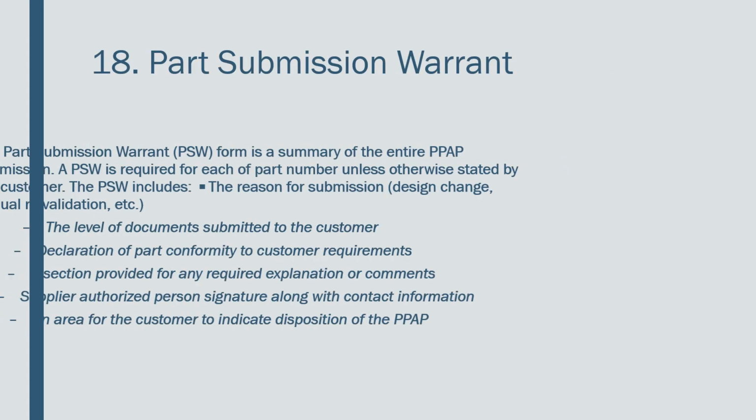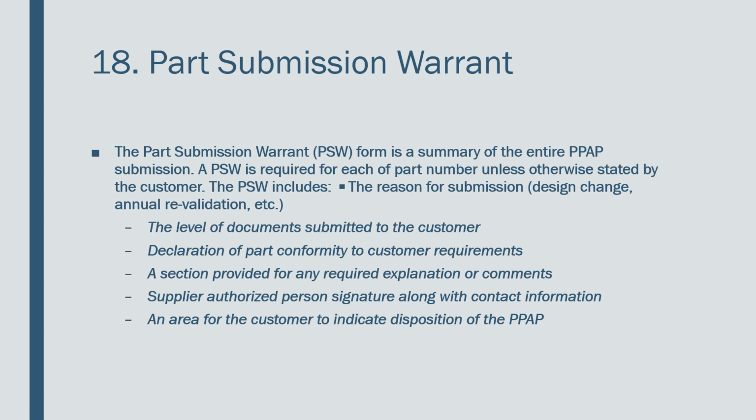The last and final element of PPAP is part submission warrant. Part submission warrant, we shortly call it PSW. PSW is a form. It is used to summarize the entire PPAP submission. A PSW is required for each part number unless otherwise stated by the customer. It includes the reason for the submission, design change or annual revalidation or engineering change or